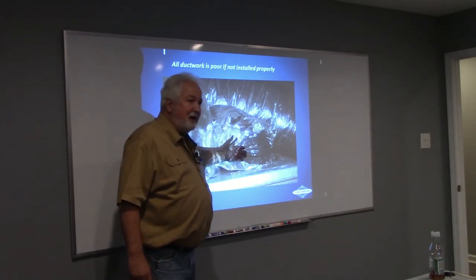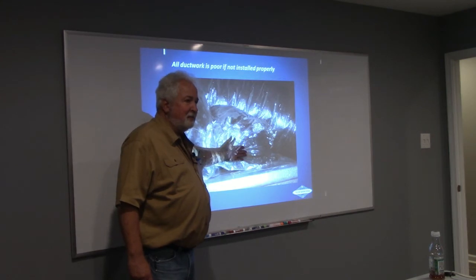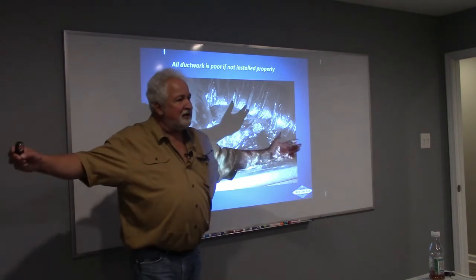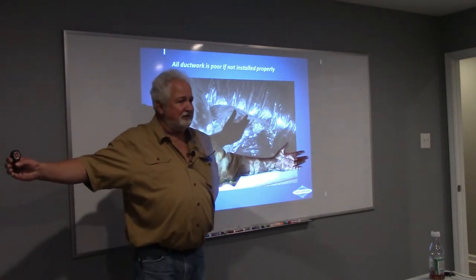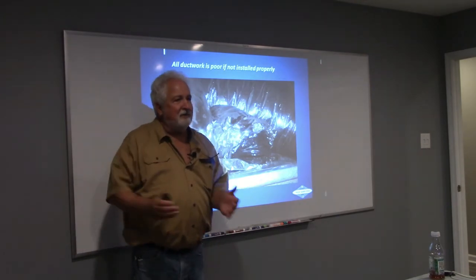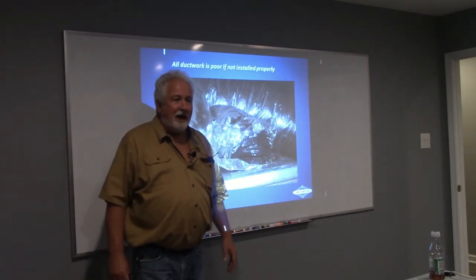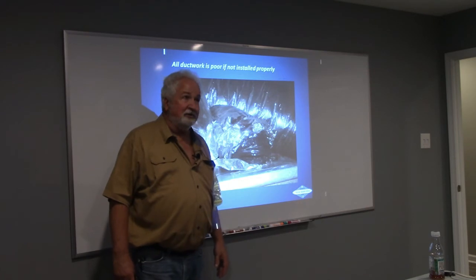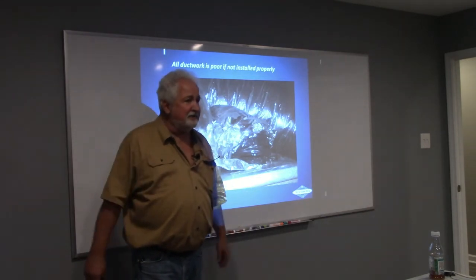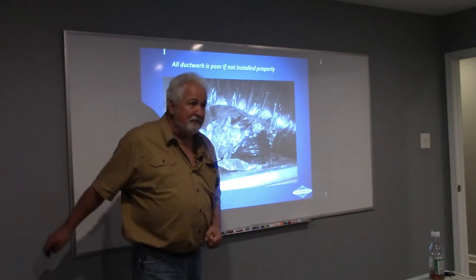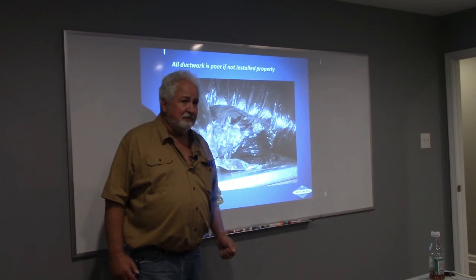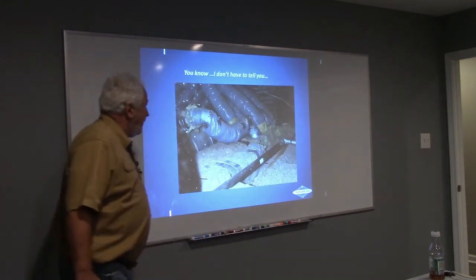If I have supply air leaks, what's going to happen to that home? Negative pressure. If I have it in negative pressure, what's going to happen to all that moisture that's outside? It's coming in. If I'm sucking moisture from outside, I don't care what kind of air conditioner or dehumidifier you guys are putting on there. If you're sucking it in fast enough, you've got more water coming in your boat than you can bail out. Does that make sense? Yes. Cool.